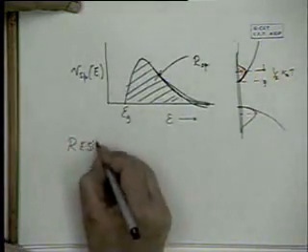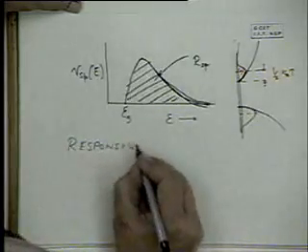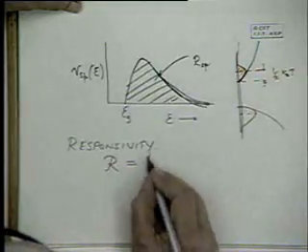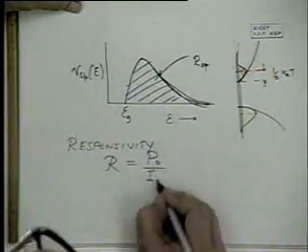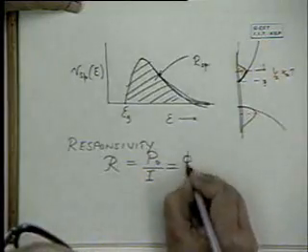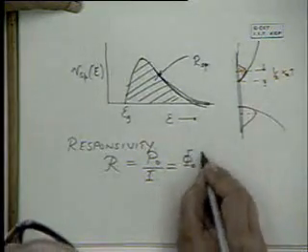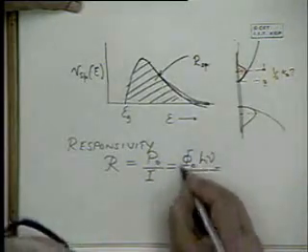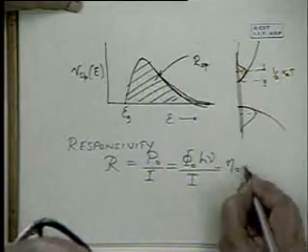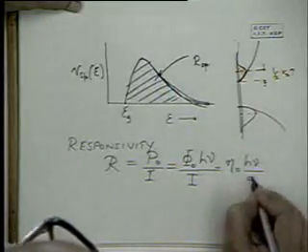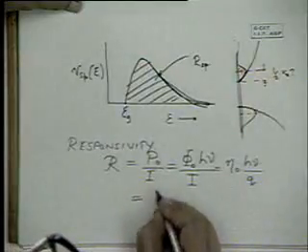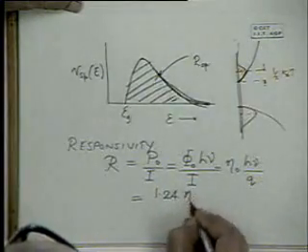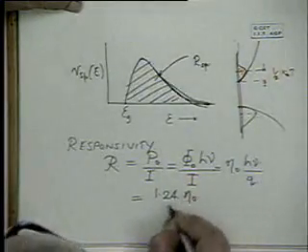And the responsivity, which I've defined before for detectors, responsivity for emitters is just R, the ratio of the power output to the current in, which is power output is the photon flux into the energy of each photon over I. And so this is eta_0 h nu by q, and we have a similar expression for detectors, 1.24, because h nu we know is 1.24 by lambda.